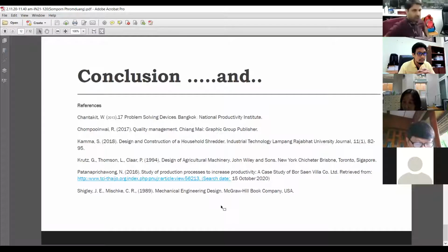For my conclusion, the researchers created this project to explore the production of precast concrete slab and design a new type of mortar box. The result showed that the handhold type was the best redesign because no mortar infiltrates into the mortar box. Therefore, the box damage rate is decreased, resulting in a more efficient production process. And that's all for me now. If there are any questions, please.